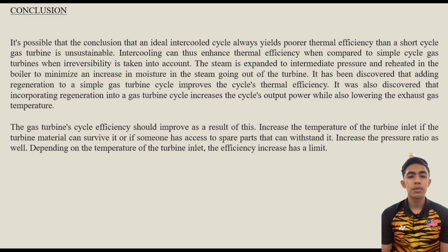Conclusion. The conclusion that an ideal intercooler cycle always yields poorer thermal efficiency than a simple cycle gas turbine is unsustainable. Intercooling can extend thermal efficiency when compared to a simple cycle gas turbine, when one takes into account the steam being expanded to intermediate pressure and reheated in the boiler.